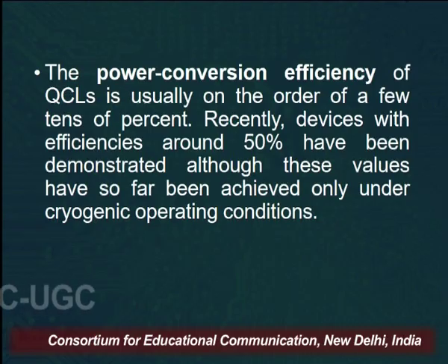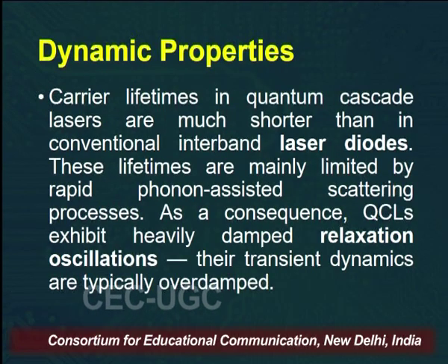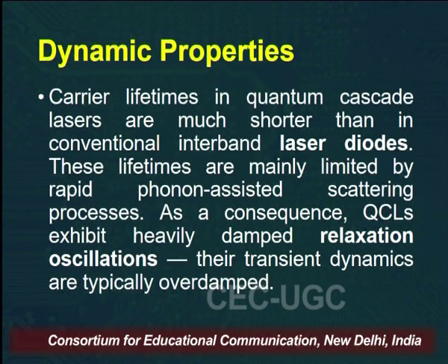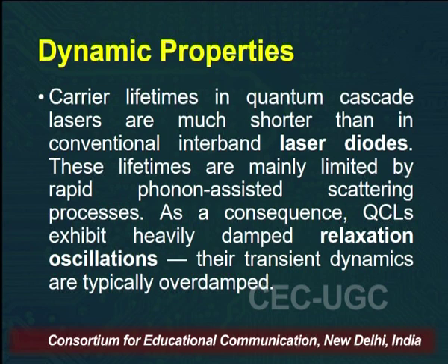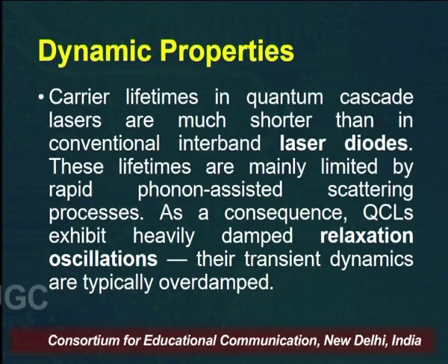Another property is the dynamic properties. What are these dynamic properties? We have relaxation oscillations. Carrier lifetimes in the quantum cascade laser are much shorter than in conventional interband laser diodes, much smaller compared to other diode lasers.